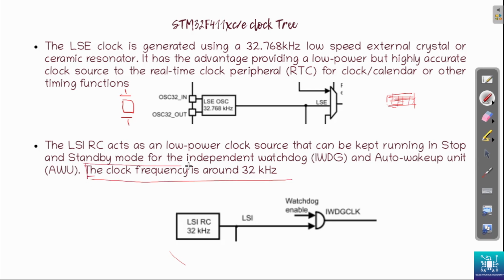I've just kept it here to mention those, but in this version of our course, we are not going to use these clocks, but it is better for you to know about this. So we have LSE oscillator and LSI-RC, and these are all parts of the clock tree only. I've just cut those diagrams and pasted here, but these are parts of that particular diagram only. We have already started breaking down the diagram into separate components so that it is easier for us to understand and follow. Since we are not using these two clocks for our application, we can just rule these two sections out for now.